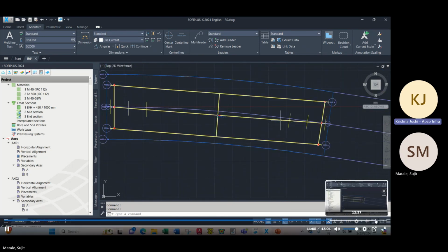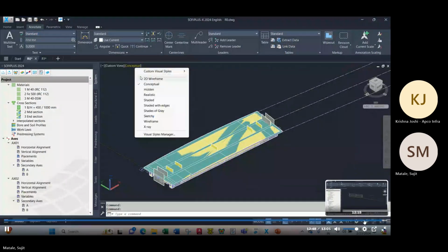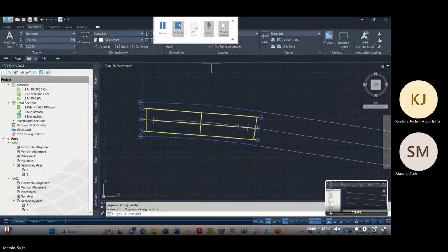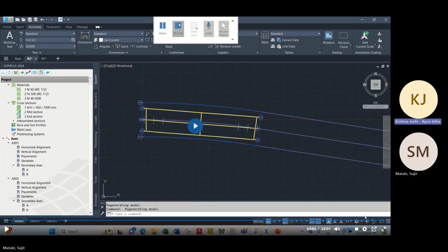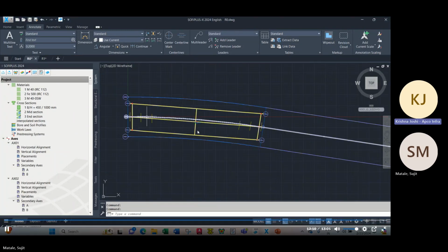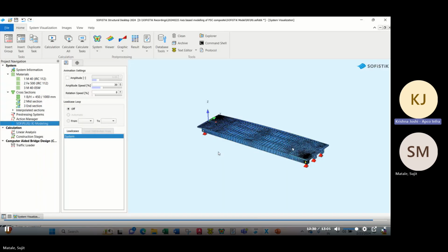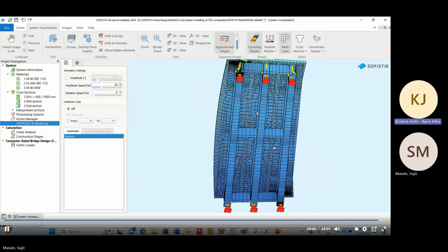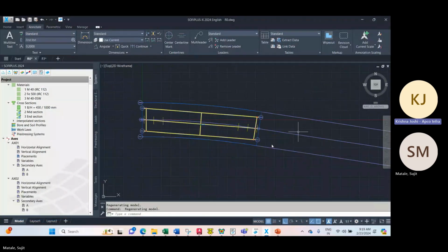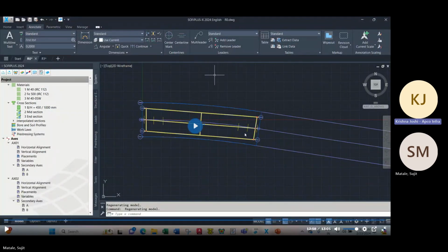And let's see finally how the model looks. It was straight and I made it curved. So now that it is curved already, I can make it straight. I can also change its length. Once you change it to straight once again, you define the geometry back to the straight one. The diagram is simply there. You have to bring it to zero. So what you will have to update in the parameters is that you will have to remove all rotation for the diagrams' placements.